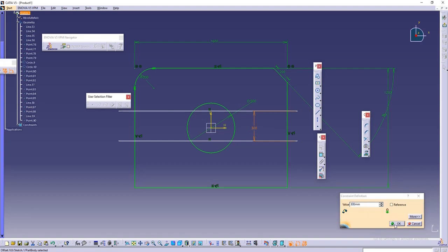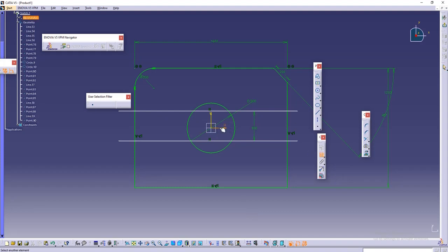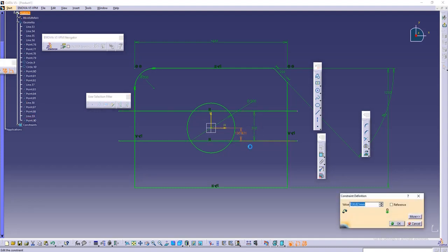That is done. Still it has not turned green. So what's the issue? It is not constrained with this one, so I need to give some reference from here to here. Now you can see it is converted. Even now it is advantageous: this is 300, so if I want to create this half in the center, it should be 150. Done. So now it is in the center.